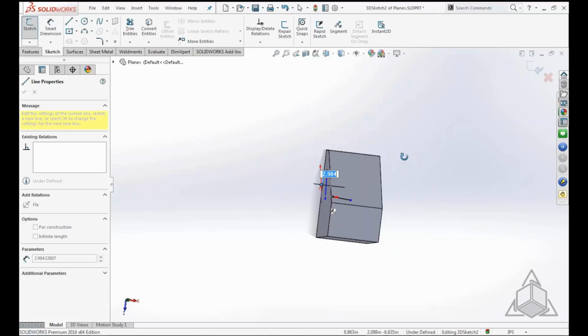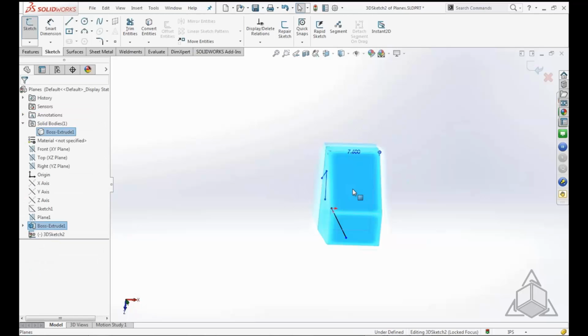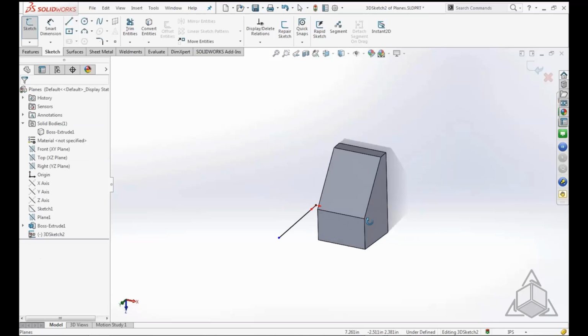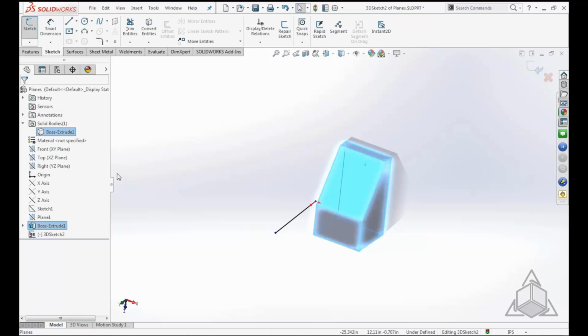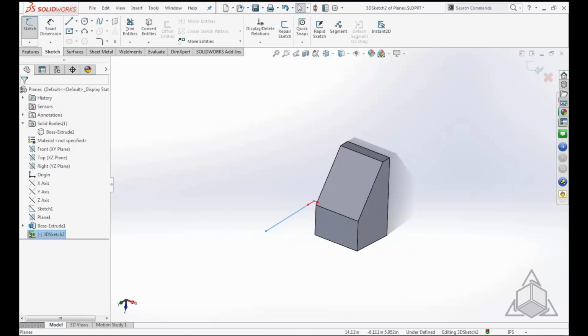Every once in a while you'll get it where it doesn't seem to want to move to a particular plane there. So what I do sometimes is I'll pre-select it, or I'll just jump in and out of the sketch, and that does seem to help it a little bit. But just keep in mind that you can use multiple surfaces of a model. You can use planes from a model, and you can create your own planes when you get into a 3D sketch.